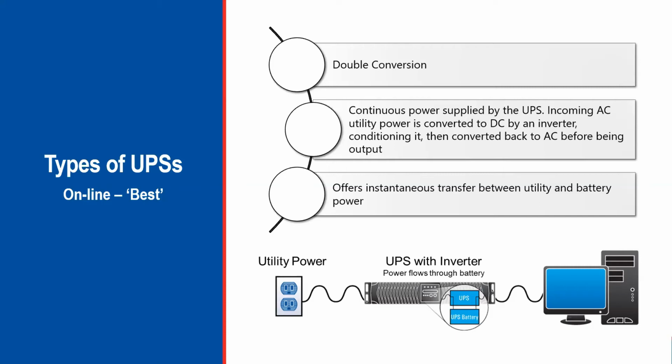But more importantly, there is no switch over time. Unlike the other solutions that you see, there's no transfer time, whether it's on standby or during battery. The online UPS is always online, and it's always conditioning power. So you will have a true sine wave from input to output.